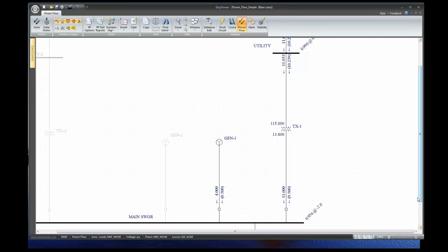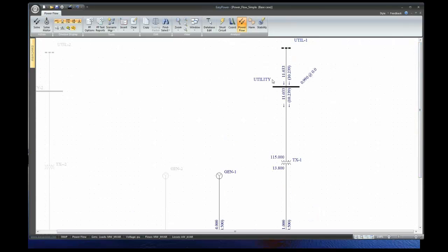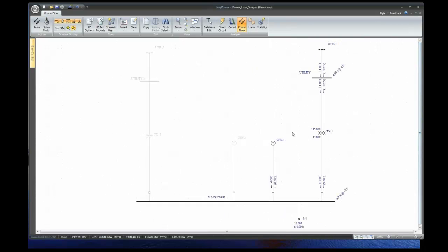Now the utility may not like that because they end up providing less megawatts and more VARs, and they don't get paid for VARs either, other than your power factor penalties. So there's a little bit of negotiation that goes on back and forth about how you're going to operate that generator when you have a cogen system. So just keep in mind, you have to be careful when you're operating these in PV when you're in parallel with a big grid.